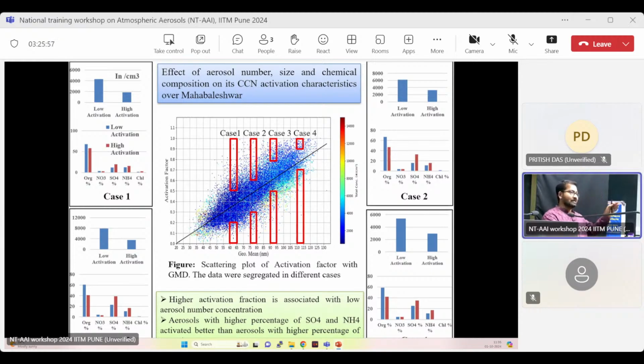So it's basically N, the total number concentration, root of the individual sizes raised to the power of their number concentration. So it gives a fairly good estimate of your mean size, because in a size distribution field you cannot use a linear mean function. You have to use a multiplication function in order to get this mean diameter. So we term it the geometric mean diameter, for different kinds of aerosol size distributions.